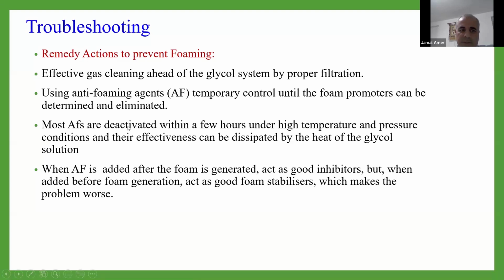Most anti-foams are deactivated within a few hours under high pressure and temperature conditions, and their effectiveness can be dissipated by the heat of the glycol solution. If we don't have a foaming problem and we add anti-foam, this anti-foam can act as a foam promoter. So anti-foam should be injected or added only after foaming problems appear.